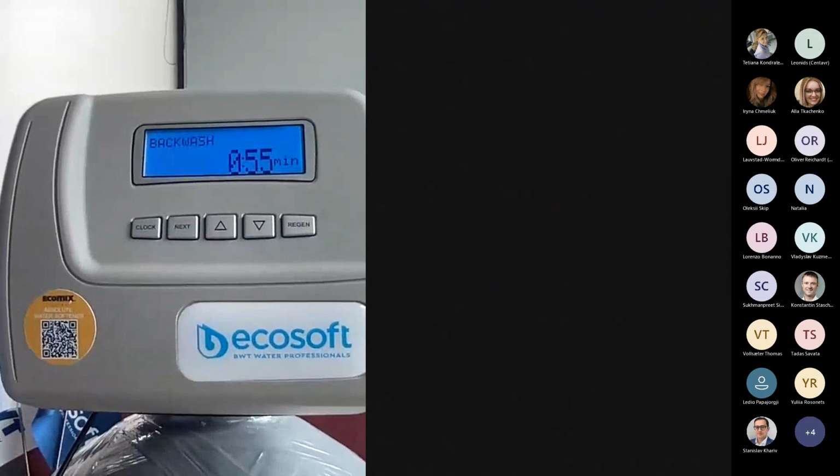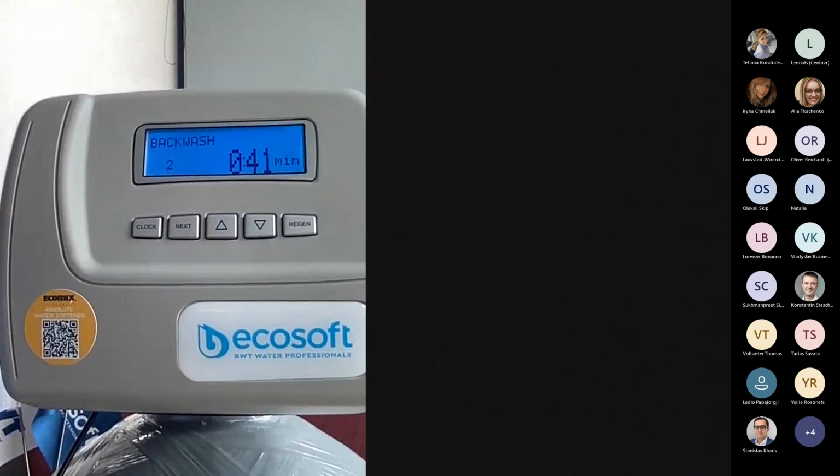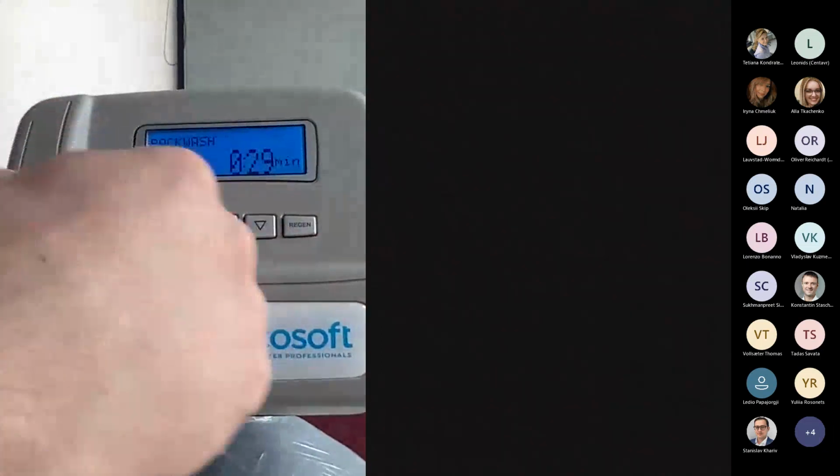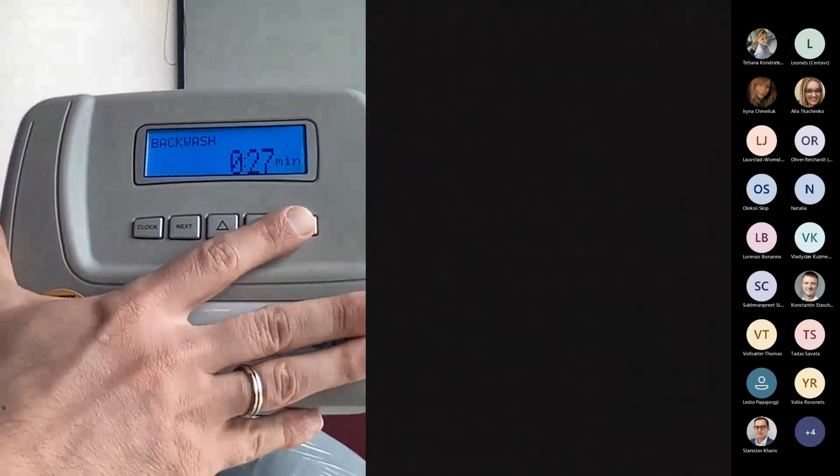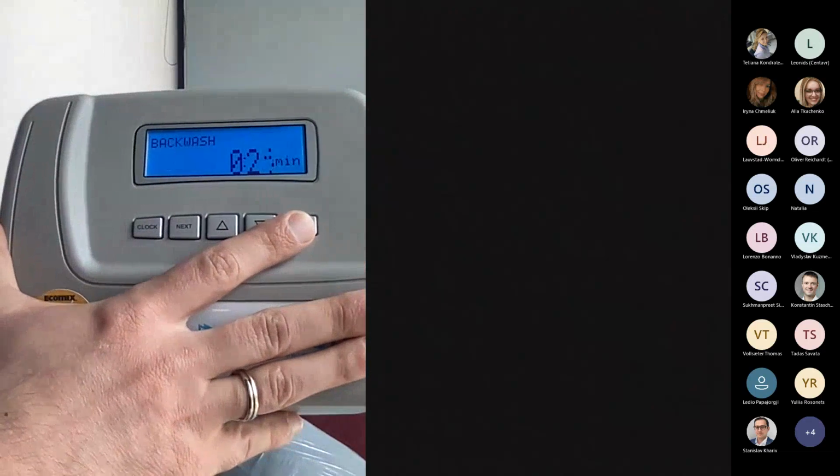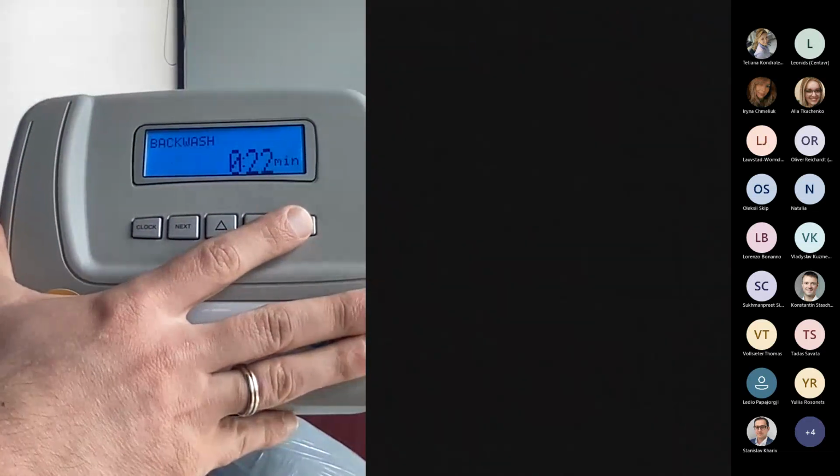The technicians use this feature when they want to check how each stage of regeneration is taking place. You will need a minute or a few minutes to check if the backwash is going fine. During the brining, we check if there is a suction of brine. This means you can exactly check how the system would operate, meanwhile you are not servicing it.